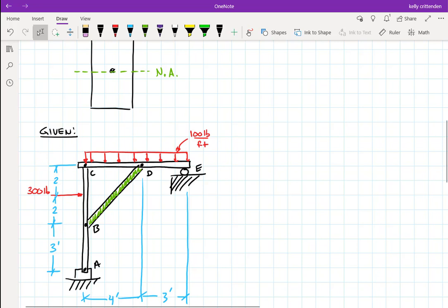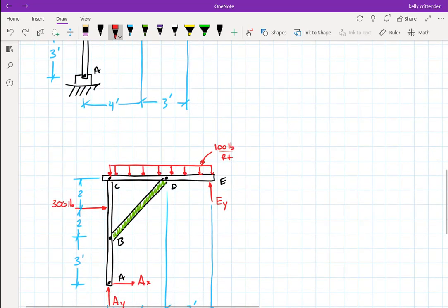So if that shelf was at an angle, then the reaction would have to be perpendicular to that shelf. That is the constraint on those rollers: the reaction should be perpendicular to whatever you're rolling on. And here, the little shelf is horizontal, so I can make the reaction vertical.